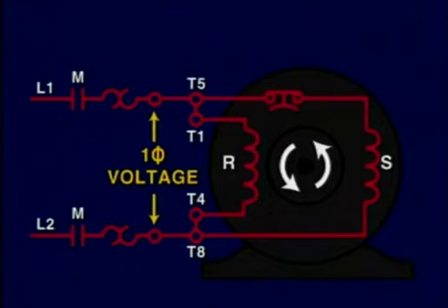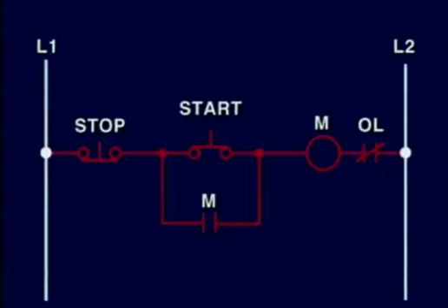Since there is only one phase voltage at its terminals, it can be assumed that all its control circuits are working properly because the starter coil is maintaining the motor energized. The hum indicates a problem with the start or the run windings, since the motor will not start if one of them is not working. The probable cause can be an open in one of the windings.